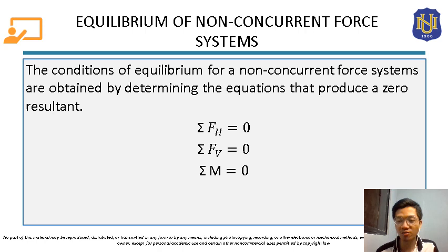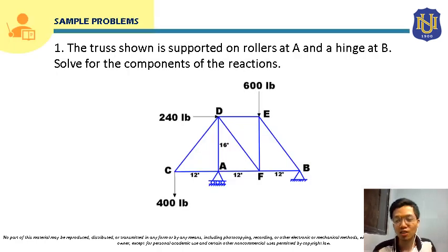Since we have here three equations that we can generate, we can solve non-concurrent force systems that have three unknown forces. So we can use these three equations to solve for those three unknowns. So let's start solving problems now about equilibrium of non-concurrent force systems.